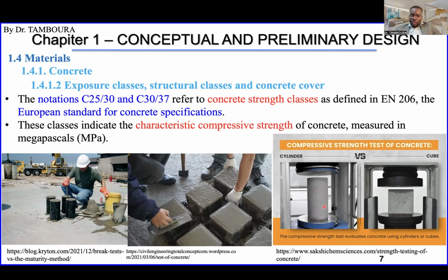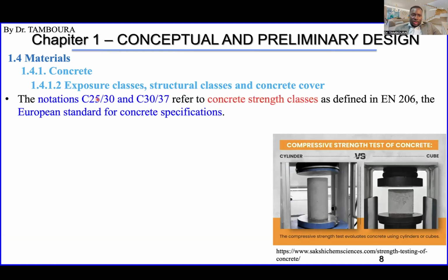It will give us something like this. The sample will be obtained after 28 days. We can then make a compression test and find out the compressive strength of this concrete. This is the cylindrical one, and this one is the cube. Okay, cylinder and cube.